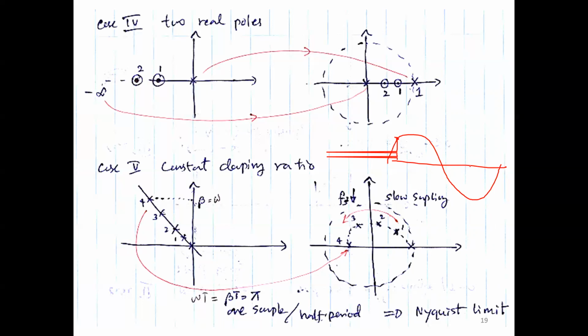Maybe you are late, and you take the second sample right over here. If you continue taking samples like that, with more than 180 degrees between adjacent samples, and you try to reconstruct the waveform from your samples, you will reconstruct a very low frequency waveform. That frequency was not there in the original signal. It's a completely new frequency that you are generating by looking at your samples.